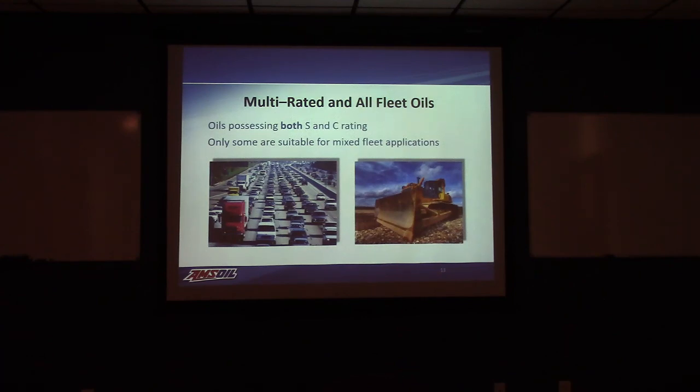They've already got a test to see whether or not that oil can function in that type of environment. So many of the new gasoline engine oils would also include this diesel spec, because they had to run that test to see how it was going to function in gasoline turbos until they were able to come up with additional gasoline engine tests to review that as well. So that's why you see some of that mixture on there.